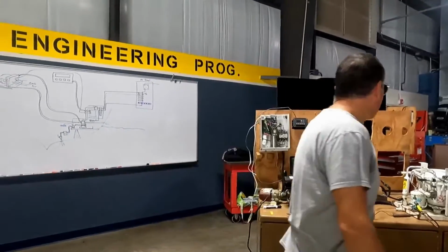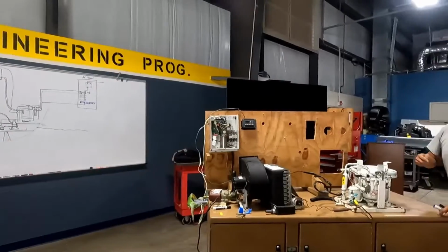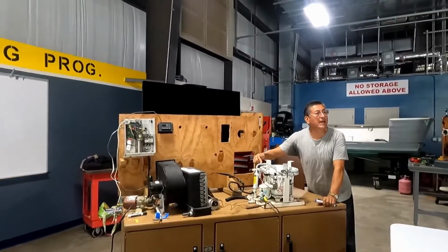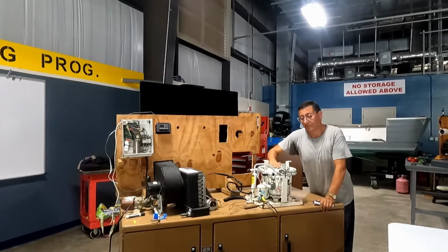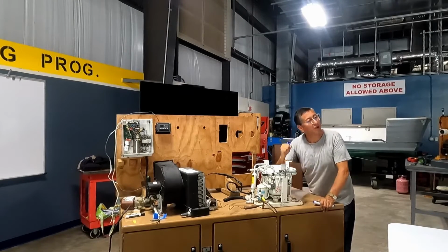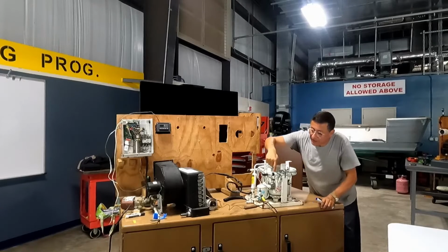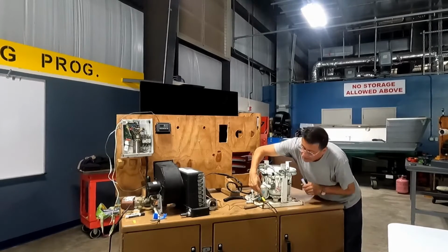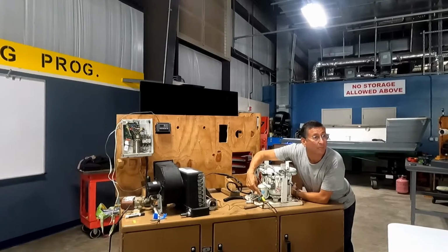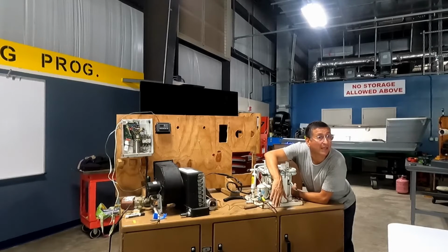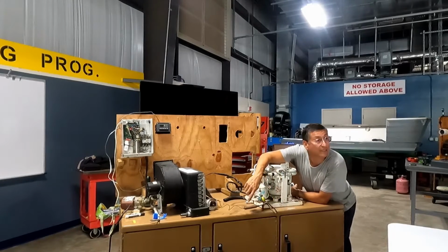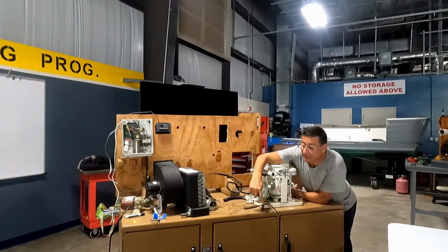I am going to follow again the path of the refrigerant. Okay, guys, look at the path of the refrigerant. The refrigerant enters, blue color, you see, at low pressure in the input feeding. The compressor compresses the refrigerant. In the output feeding, red color is going out, compressed at high pressure and high temperature. This line, when you touch it, will be hot. It passes through the filter and dryer, reducing the temperature. After that, the diameter is reduced.